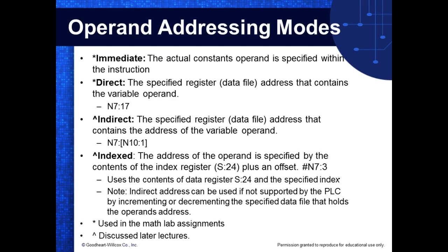Now, where can you find more information about the addressing modes supported by a PLC? In the manual. So you just go in there, bring up the PDF file, type addressing modes, it'll pop up and it will tell you all the addressing modes supported. Every PLC is going to support different addressing modes, and it adds more power to the way you address these operands, right? We can point them, we can move them, we can increment an address, we can scan through tables. We use tables a lot. We'll do this especially when we get into sequencers and stuff like that. We can save stuff automatically. It's really, really neat.